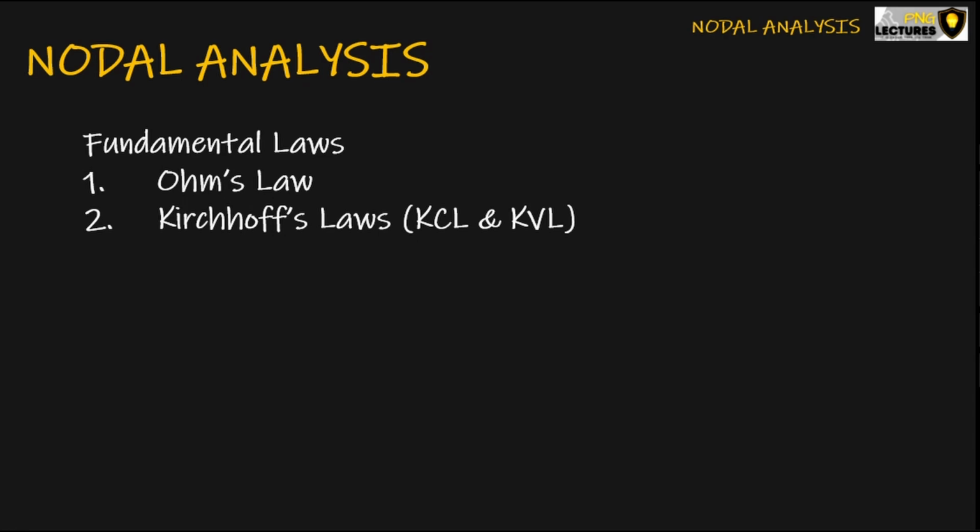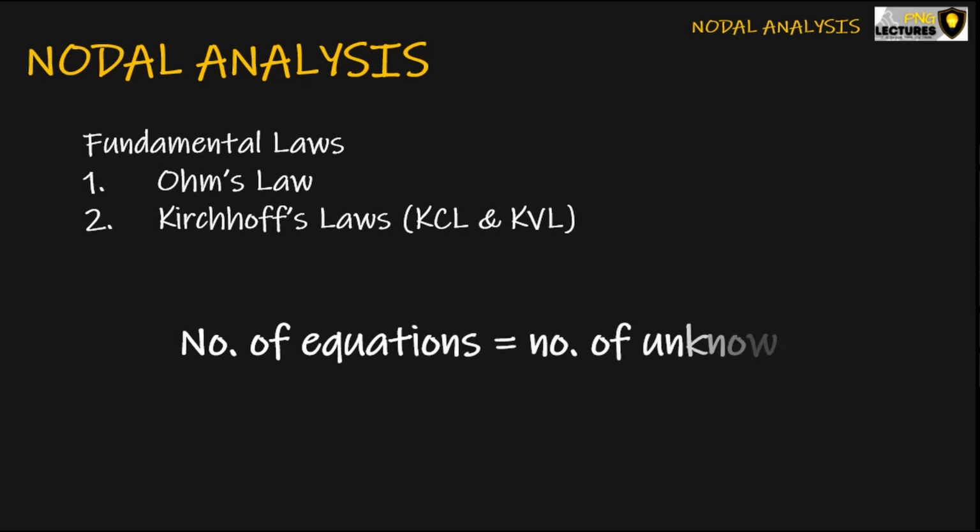However, as mentioned, it should be noted that the techniques presented by Kirchhoff require intensive algebraic calculations, since the number of equations needed is dependent on the number of branches in the circuit. To address this concern, nodal analysis simplifies the process by choosing node voltages instead of element voltages as circuit variables. Since the number of nodes is always less than the number of elements, nodal analysis reduces the number of equations one must solve simultaneously.